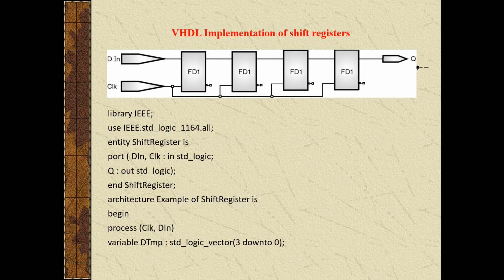For parallel to serial conversion, the 8-bit register is first loaded with the input data, and the bits are then individually shifted out, 1 bit per clock cycle on the serial output line. Hence, the output will appear in serial.